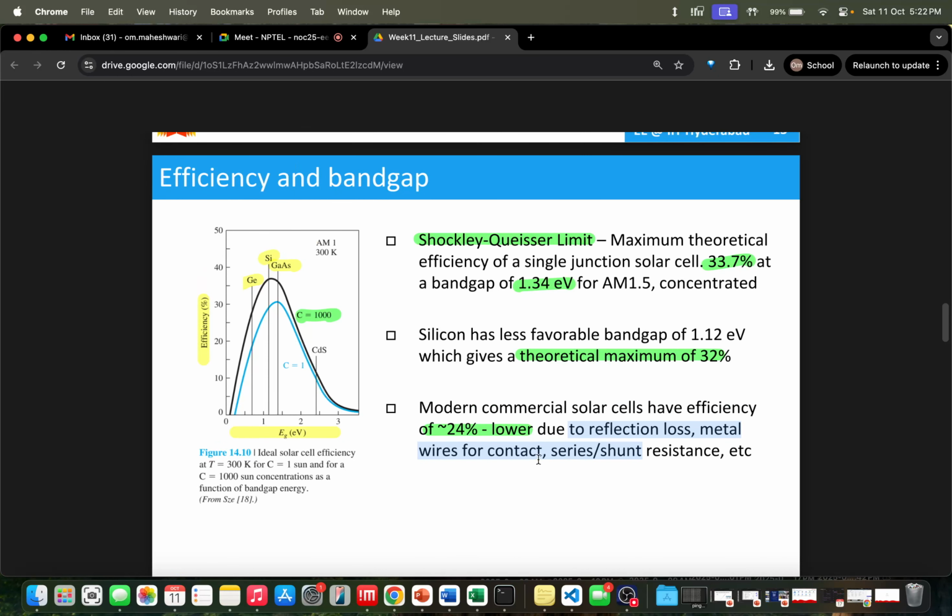So this is about photovoltaics now. If you have some semiconductor and some current is flowing through it, and you shine some light, there will be generation of additional carriers. If it's N-type, you can detect the P-type carriers also, because the N-type carriers will be small. So your J naught is the equilibrium current. JL will be the current due to light that you can detect, and JL is given by this formulation.